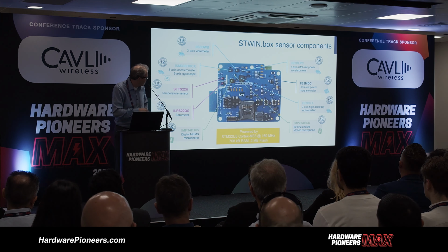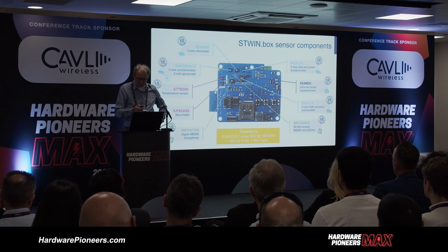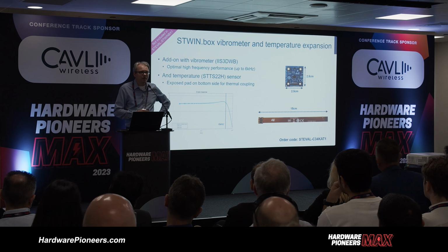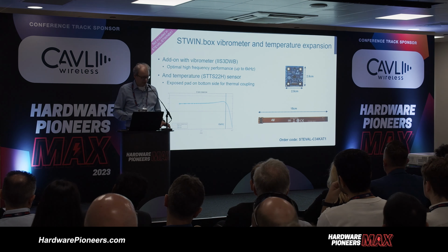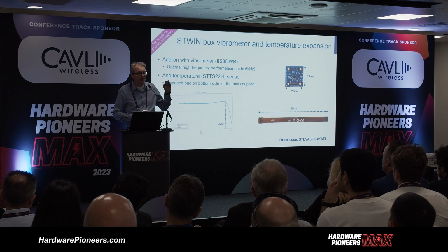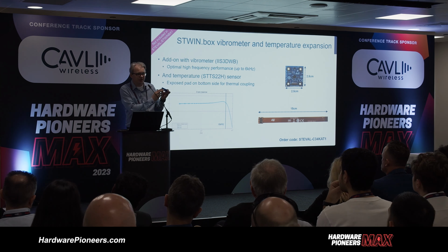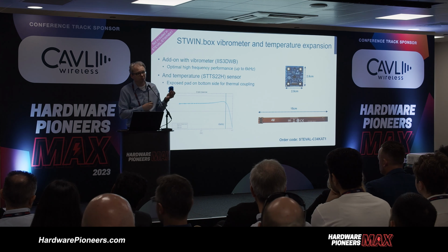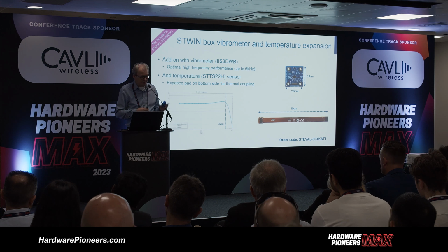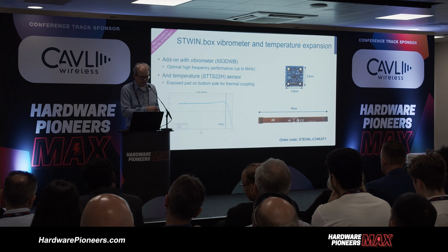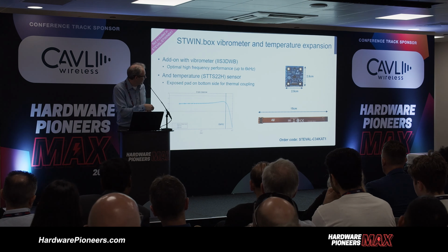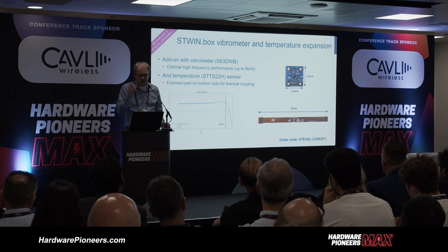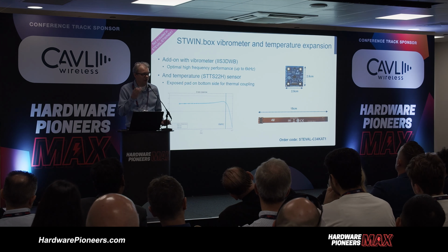And then we had the magnetometer, 2 microphones in here, barometer, and the temperature sensor. But actually, to make the vibration measurements accurately, even in this box, we can measure them roughly up to 1 kilohertz. Then you start to have different kinds of resonances within this box itself. So there's the battery inside, and in a way this is optimized to be a low-cost tool for the initial development. But in this case, we are also offering this kind of external flex cable and this kind of small board that you would then attach to your device directly, even glue it.